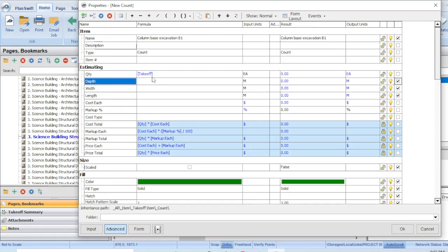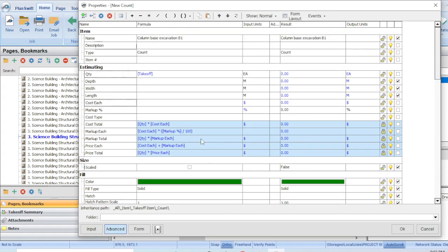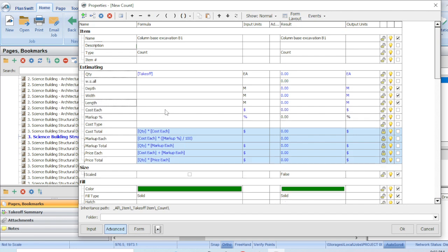You know, if you want to obtain your cubic meter, the volume of your excavation, you know the width. You have to add working spacing allowance to the width and to the length. So I input working spacing allowance, dimensions, units is in meter.